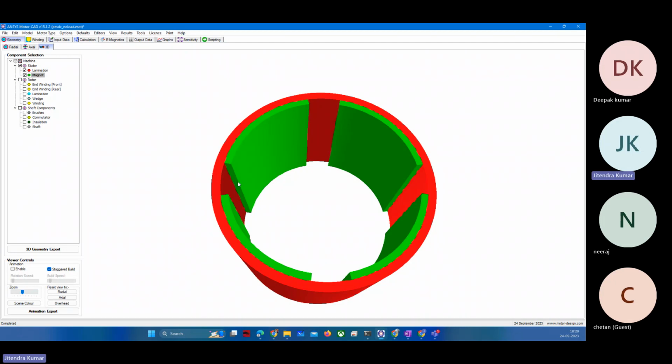So if you want to reduce the strength, you have to apply armature current in such a way that it will demagnetize this permanent magnet, right? So that's the way. Otherwise, if you want to increase the magnetic field, you can increase the magnetizing component of the current from your supply, right? Okay.